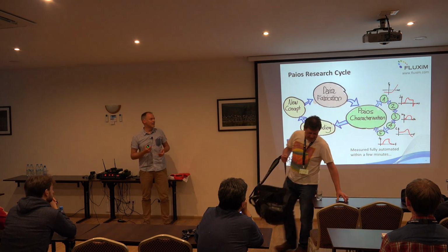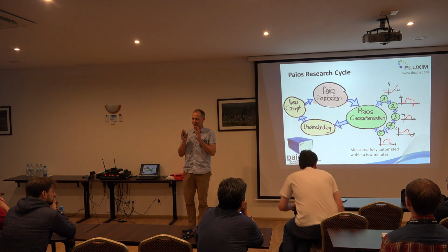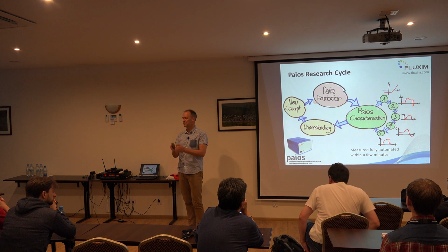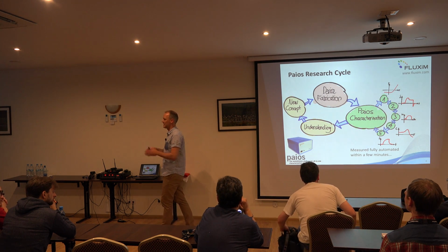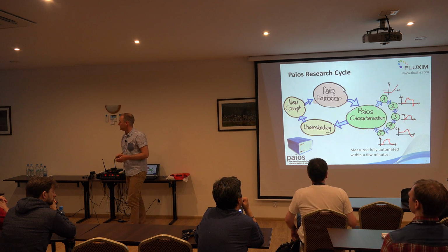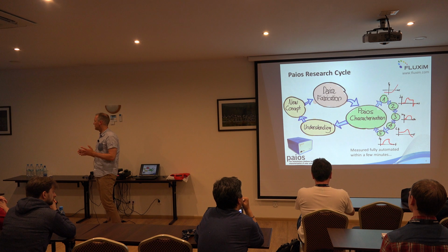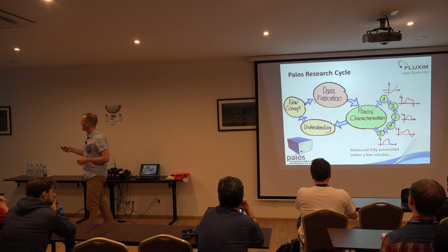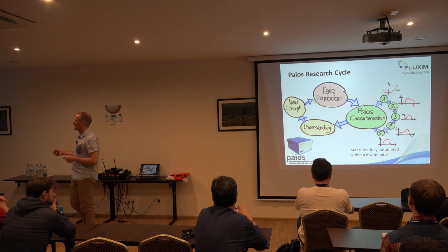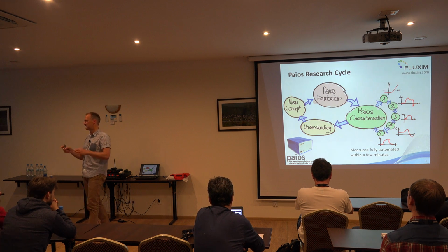So what we're trying to propose is, instead of going to different laboratory rooms, where in one you measure the IV curve, in a second room or instrument you do impedance spectroscopy, and in the third lab room you do transient electroluminescence, which would be classical, we now propose to do all at once without changing cables and without changing contact resistance and different systematic errors.